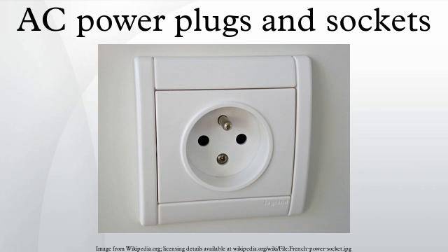CEE 7/4, Type F, commonly called the Schuko socket, has a recessed round shape with 2 symmetrical round sockets and 2 earthing clips on the sides of the socket. The Schuko connection system is symmetrical and unpolarized in its design, allowing line and neutral to be reversed. Its dimensions are compatible with CEE 7/5 except that the female earth contact is omitted. The socket also accepts Europlugs and Series 7/17 plugs. It supplies up to 16A.